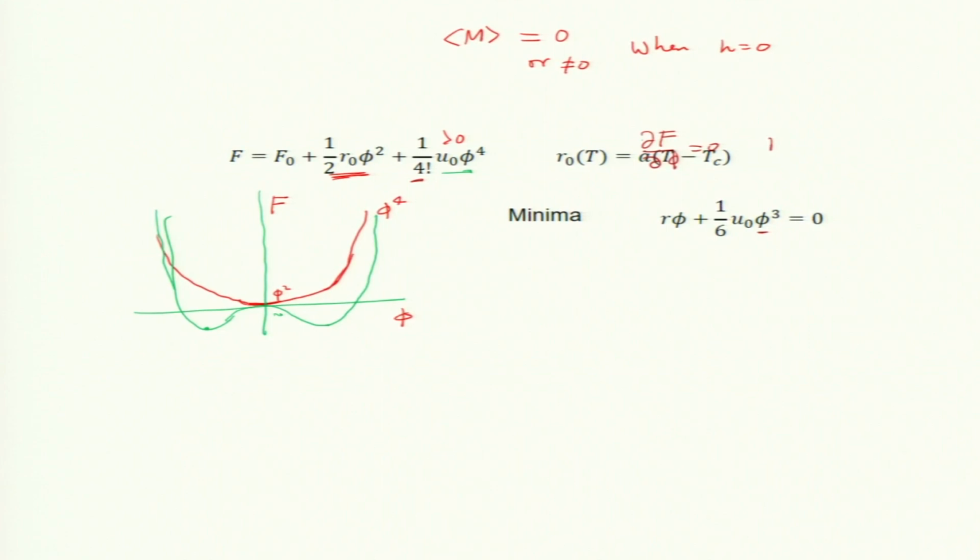And phi is a constant, please remember. At a given temperature I am having some phi, okay, and of course, it will go to the minima. We know the free energy minima is what is chosen at a given temperature. So, the solution will be either this or these, one of the two. There will be a unique solution at a given temperature. Now, what are the solutions for this cubic equation? One is phi equal to 0, in fact, this is pretty simple theory, and other is this.